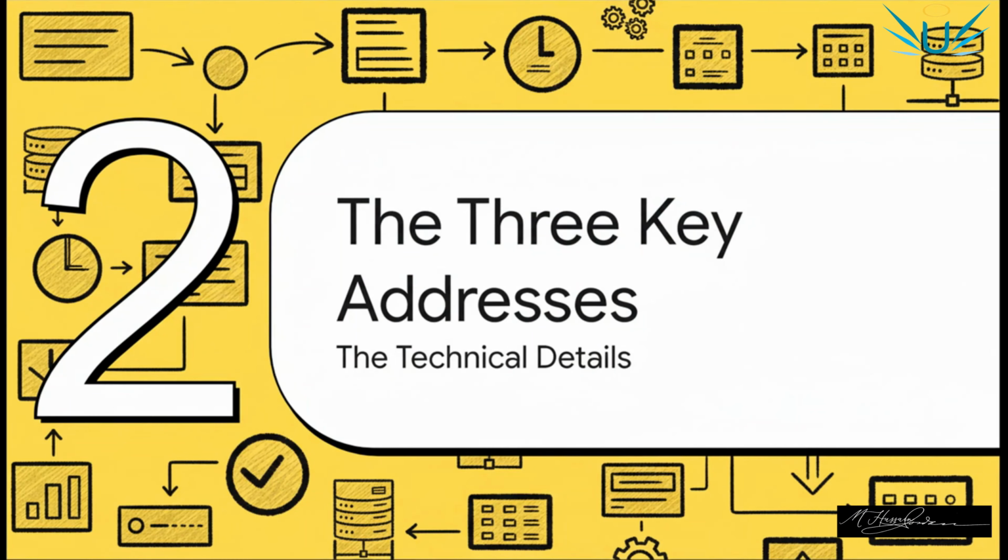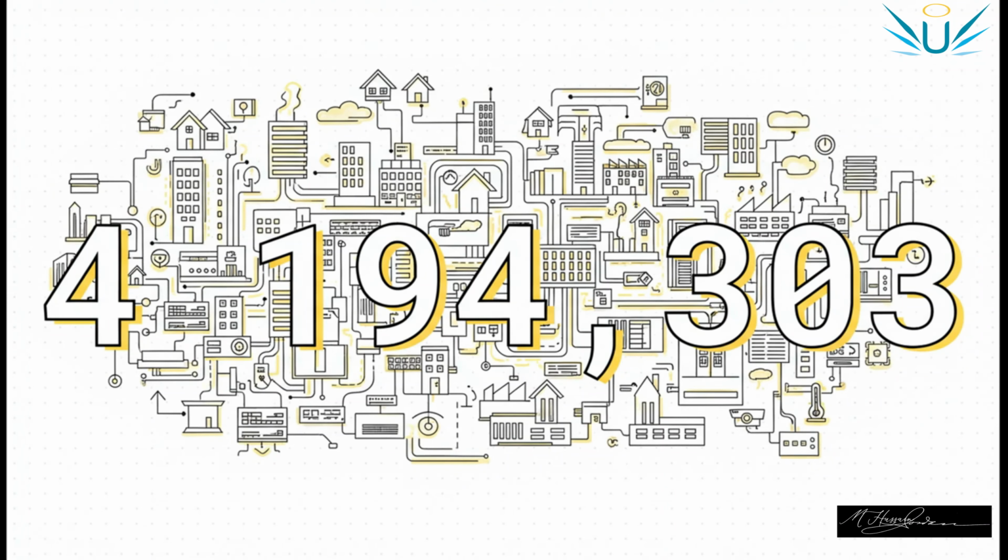All right, now that we've got the big picture with our postal analogy, let's get into the nitty-gritty. This is where the rules of the road are, and trust me, they matter a lot. So remember that device instance number, the unique name for every device? Well, how many possible names are there? Check this out. Almost 4.2 million. That is a huge number. And that's exactly the point. It's so big that you can pretty much guarantee that every device in every building on the planet can have its own unique number. No overlaps, no confusion.